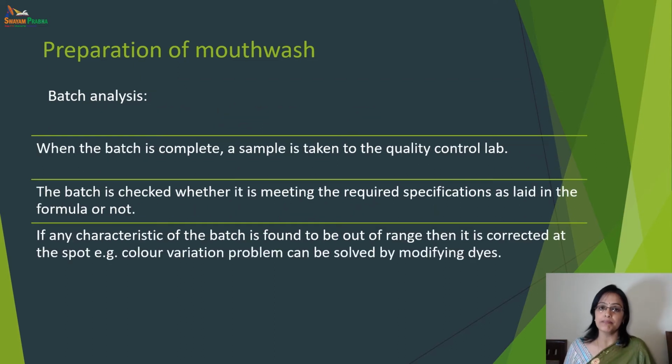So next is batch analysis. Once the batch is complete, the sample is taken to the quality control lab. The batch is checked whether it meets the official, standard specifications as per the formula or not. Then the quality control chemist runs the viscosity, pH determinations and other related parameters.